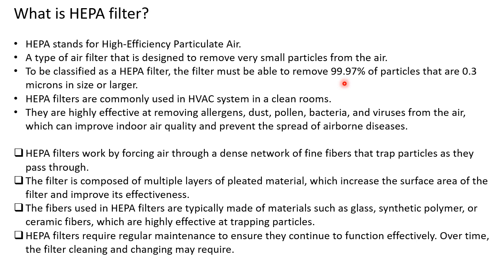HEPA filters are commonly used in HVAC systems in clean rooms, and they are highly effective at removing what? Allergens, dust, pollen, bacteria, viruses from air, and thus they can provide very good quality indoor air and prevent the spread of airborne diseases. Now HEPA filters work by forcing air through a dense network of fine fibers that trap particles as the air passes through.